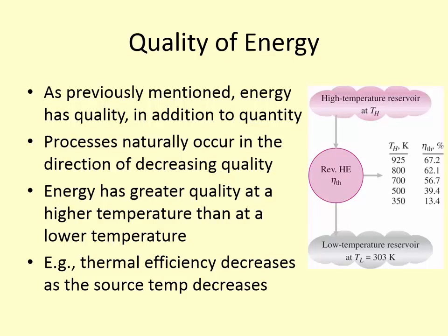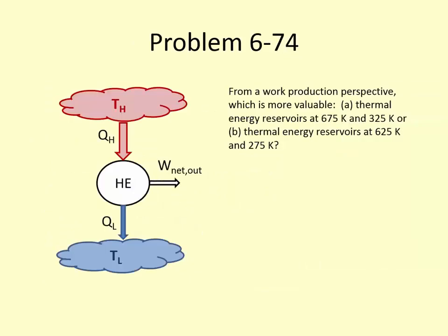And so similarly, if we have a high temperature reservoir, we want to do whatever we can to maintain it at a high temperature because we get more use out of that energy when it's at a higher temperature than we do when it's at a lower temperature. So the thermal efficiency will continue to decrease as our source temperature decreases, which is not always a good thing.